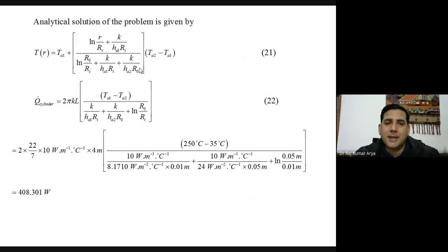The only intention is to find the derivation in terms of known variables, so nothing should be in terms of T0 or Tn+1 because those are not known to you. You only know the surrounding atmospheric gas temperatures, the heat transfer coefficients, and the position, the radius, where you want to calculate, correct or not? So just keep on changing and arranging your equation till you get your expression in terms of all known variables. That is the only logic behind it.